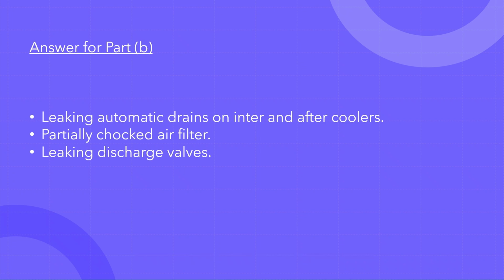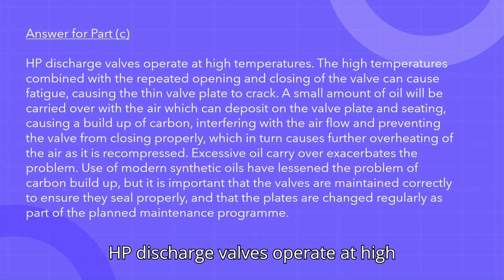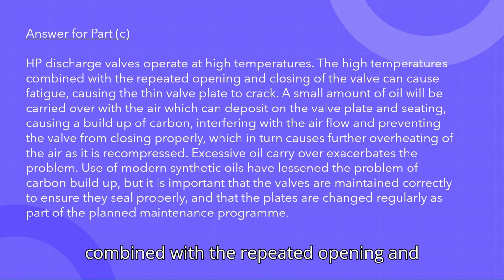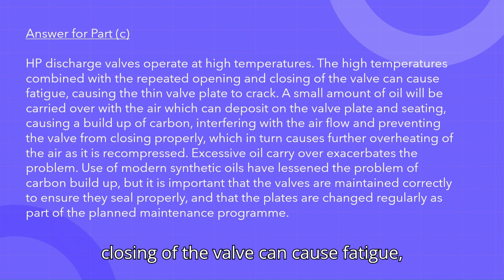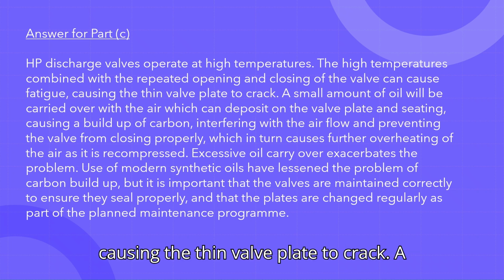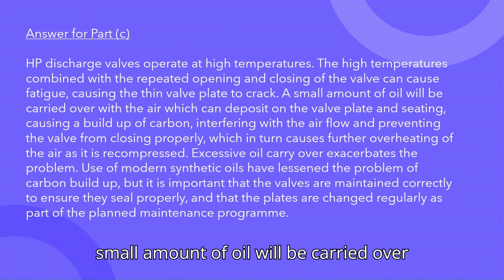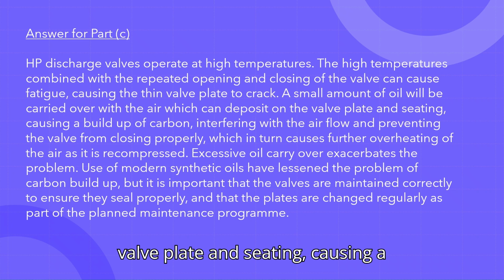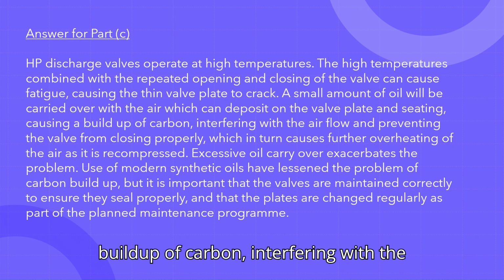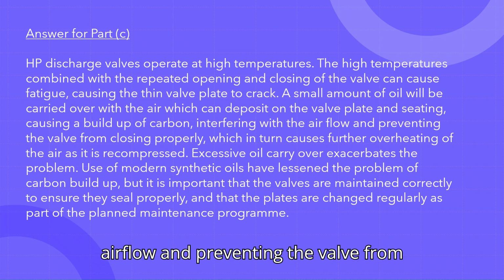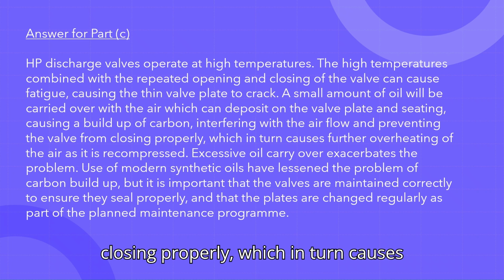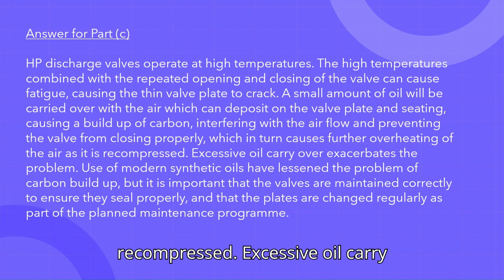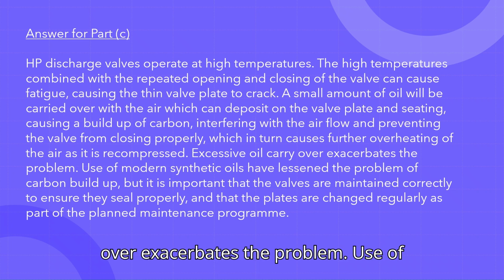Answer for Part C. HP discharge valves operate at high temperatures. The high temperatures combined with the repeated opening and closing of the valve can cause fatigue, causing the thin valve plate to crack. A small amount of oil will be carried over with the air, which can deposit on the valve plate and seating, causing a buildup of carbon, interfering with the airflow and preventing the valve from closing properly, which in turn causes further overheating of the air as it is recompressed. Excessive oil carryover exacerbates the problem.